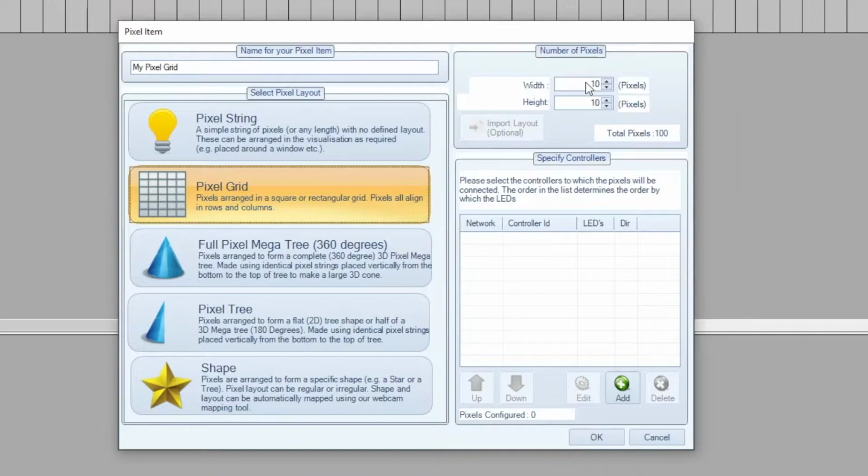You wire them together on a couple of outputs or a single output of a controller, but you must remember to power inject your additional strips or extra strings, otherwise you don't get enough power to the LEDs and they appear very dull or the whites come out sort of very yellowish. So you must remember to inject extra power.